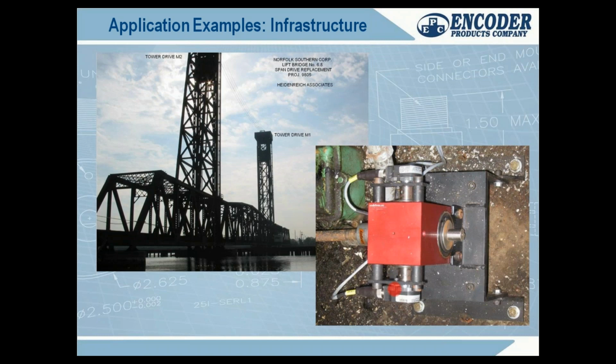And from a safety perspective, if you're on that AGV and you have an incremental encoder that's closing your loop for velocity, if that encoder ever failed, you could have an AGV going crazy on the floor and driving into people. That can't happen. So you'll see a need out there for redundant feedback. That's two discs and two reed heads. Some companies sell them in a package. You'll get a safety encoder.